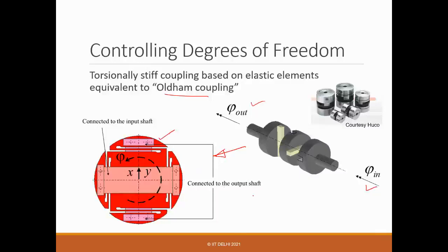The section here, the T, is just this T. If you take a thin sheet and cut it, saw it, from this point to this point, you see 4 of them. Earlier you had 3, here you have 4. But the way they are connected, they are connected through these 4 wire flexures.